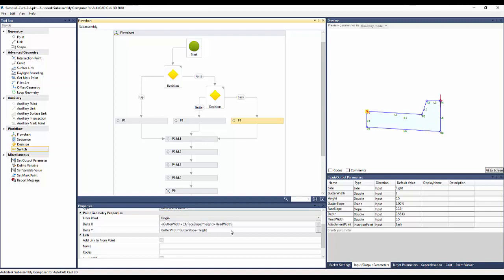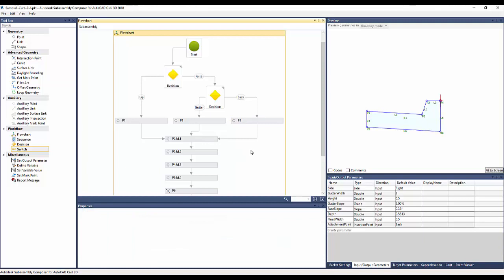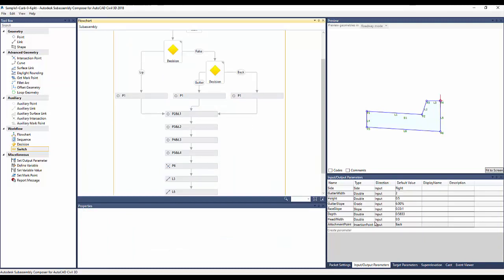Now, if you notice, I don't have any numbers in here for the most part, besides throwing a reciprocal in there. And I am a big advocate for, as a best practice, to never put any numbers inside of any of these points, almost without exception. If you have a number, give it a variable name and put it out here, because there is always a chance that somebody is going to want to change that. And if you ever have a number hard-coded in here and you got to go back in and change it and then re-import the subassembly, you've made your subassembly a lot worse, and there's almost no reason to do this.